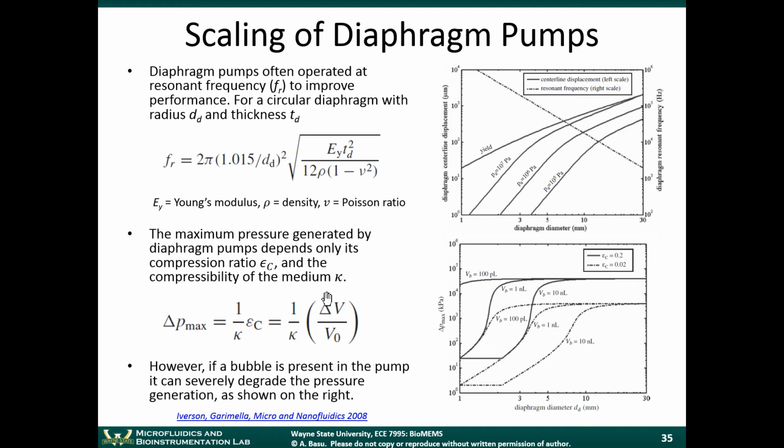So there was a big windstorm one day, and that caused the bridge to start to vibrate at its resonant frequency. And you could literally see waves going through the bridge. You can see a YouTube video of this, right? I don't want to stop class and look at that right now, but you can look at it in your own time. These gigantic waves, like the bridge, which was made of concrete and steel, was literally just undulating like this, and eventually the bridge collapsed. So when things are vibrating at the resonant frequency, the energy in the system can multiply.